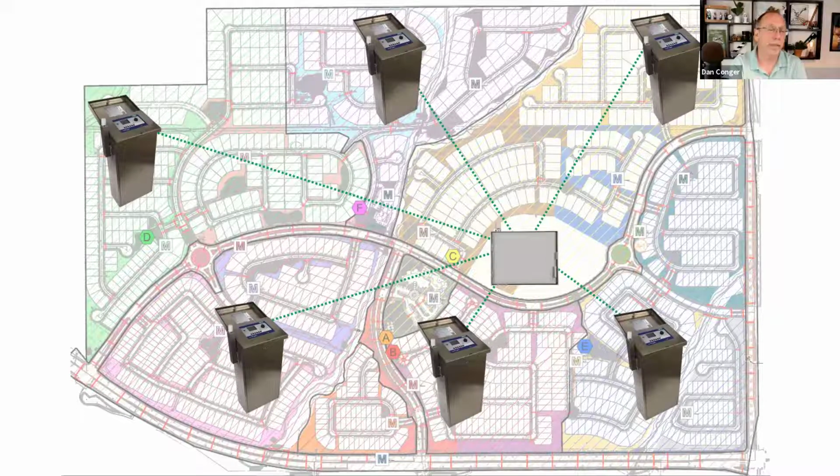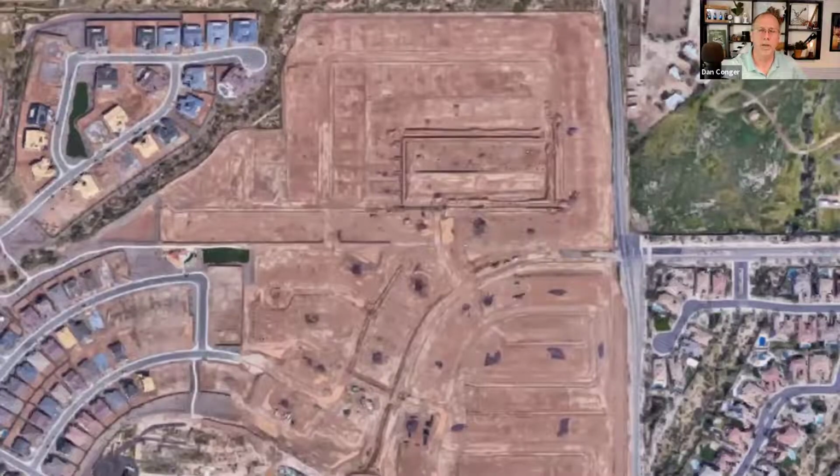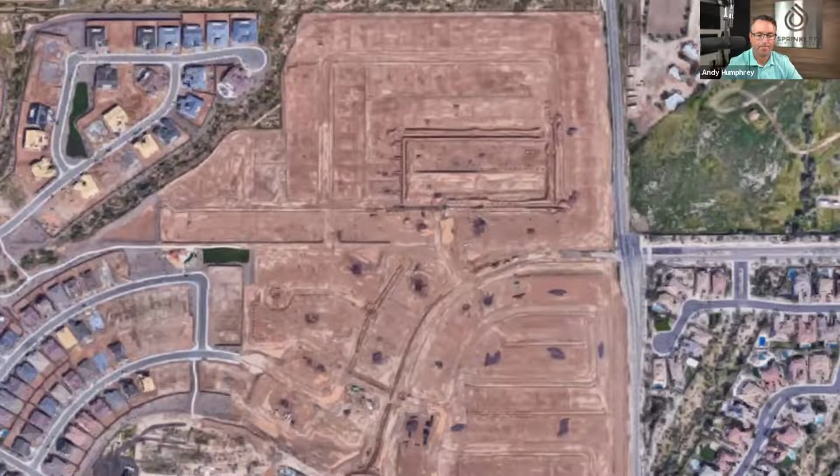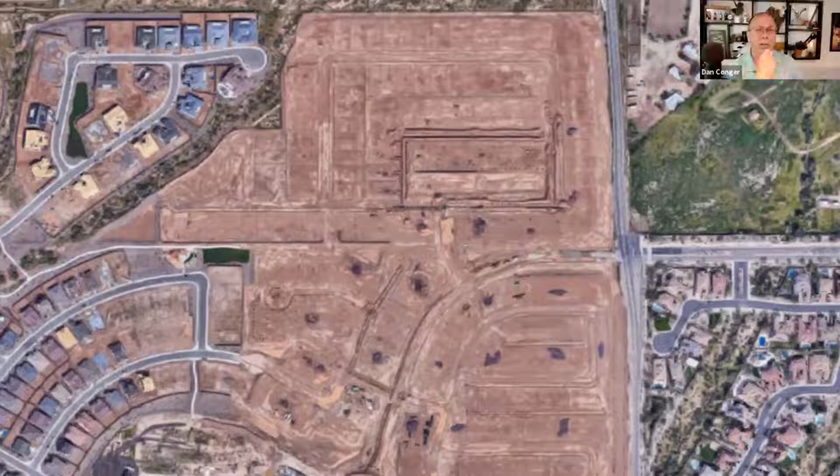Right. Absolutely. So we're not showing the hardware that's in there, but within those pedestals, they originally intended on a radio. A couple of things about radio, and we'll probably take a minute to talk about this: radio is intended generally for line of sight. And to make sure that a site's going to work, we have a qualification or survey process in which we want to test each location. And that'll help us understand the antennas and what everything looks like, right?